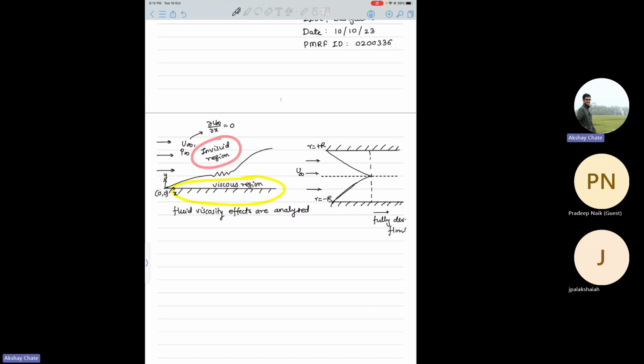because there is no change in the velocity of the fluid flow with respect to x direction, or in this case the axial direction. So yeah, I think I saw one question in the assignment which says what is the maximum height that the boundary layer can achieve in a circular pipe. So it is basically the radius of the pipe, because after that the boundary layers merge and they become like one single flow, retarded type of flow. That is one question.